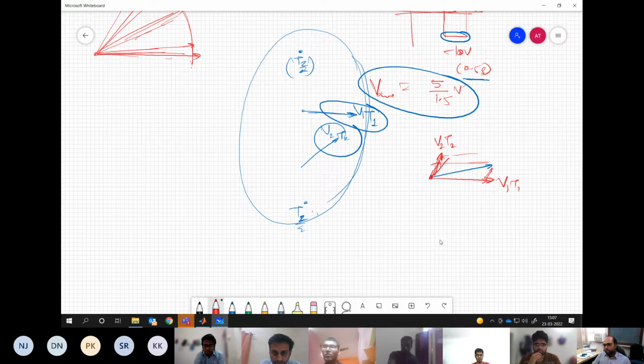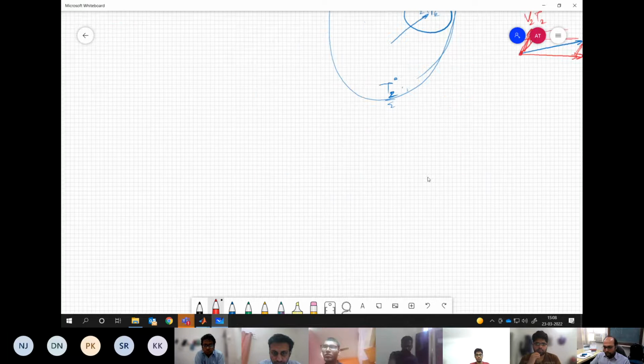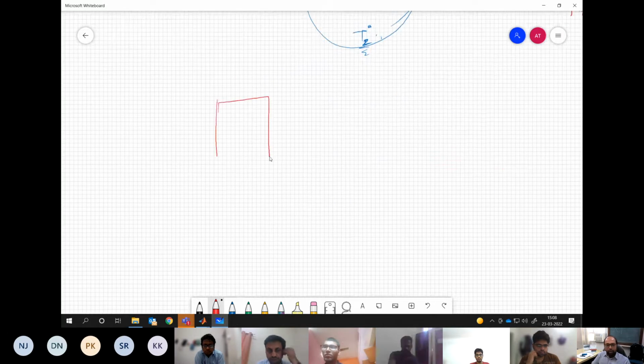So what I'm trying to say is, how do you implement a space vector PWM? I'm not saying conventional only, any space vector PWM. How do you implement it? You are given a motor, you are given a power converter. How would you implement it? Let's say you have to operate for V by F.